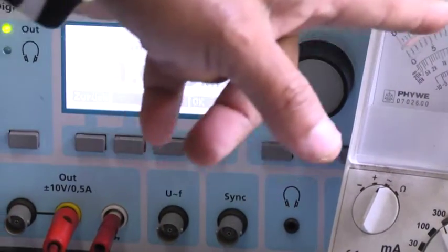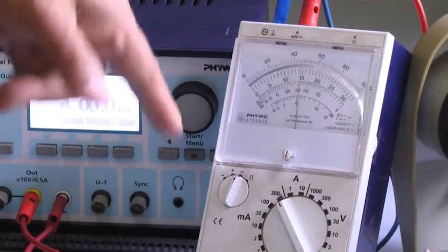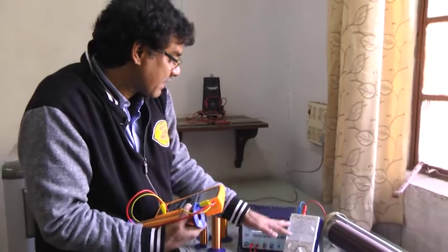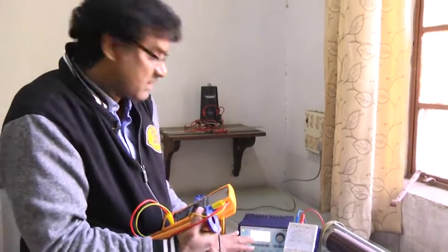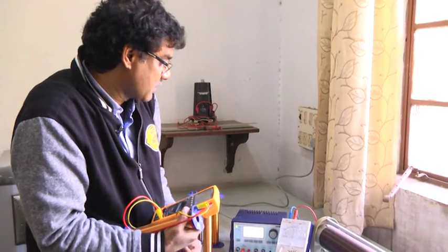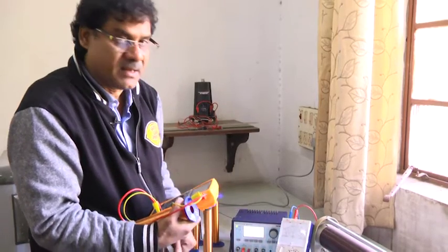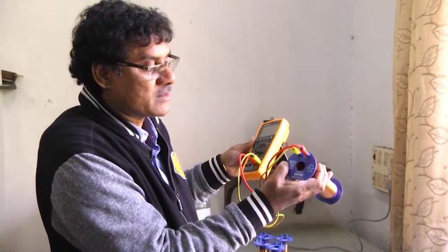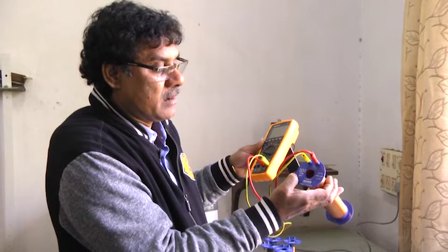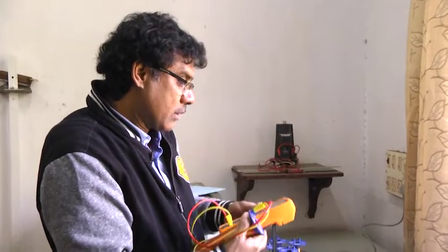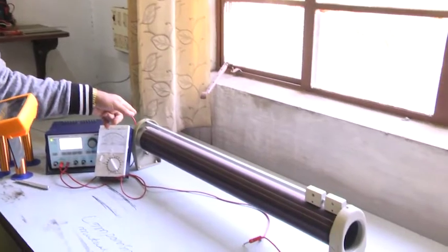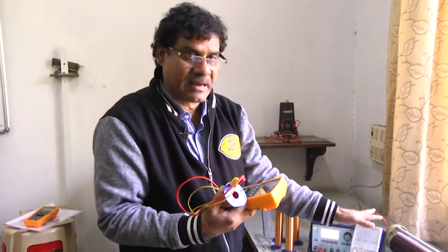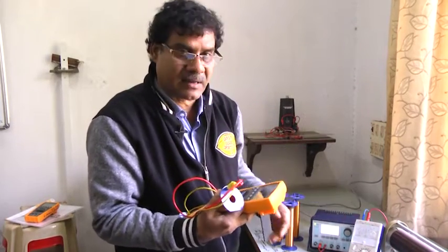If I vary the voltage, then I will be able to vary the current flowing through this solenoid. I am interested in the current in the solenoid as well as its frequency, so I have to note down this frequency, 4 kilohertz, and this current, 150 milliampere. I also have to note down the number of turns, small n is 300, and the diameter is 41 millimeter. Also the total length, capital L, and the total number of turns in this solenoid, which is already given. I will tell you what the data for this are.